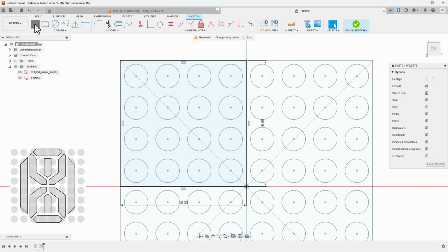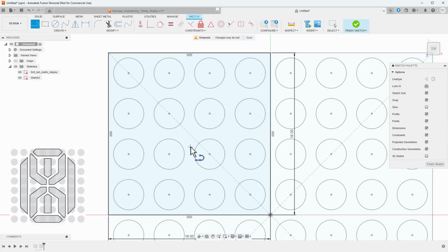And then select the line tool, and let's start by drawing the first segment, actually part of the segment. I will start with the one on the very left side, starting on the bottom, touching the rectangle so it snaps to the rectangle, then going up, making sure that this is the vertical line, then going to the right side and back to the bottom to touch the rectangle.